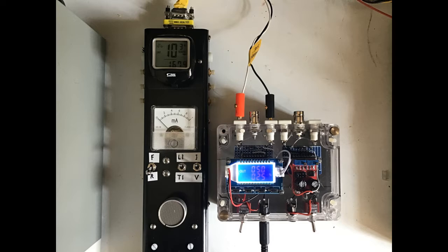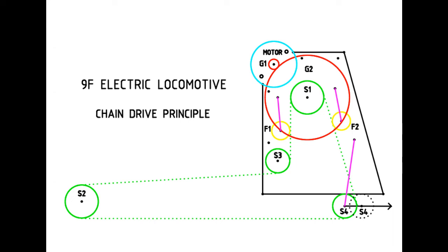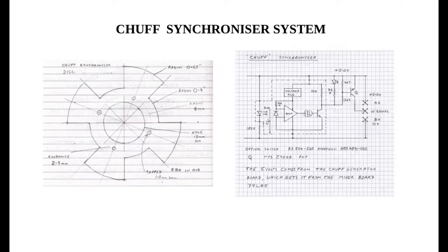I will now describe the chuff system. I was interested to see if I could produce a reasonably realistic sound of the steam exiting the cylinders synchronous to the piston position. The first decision was to use the same sprocket size for the centre axle and the sprocket in the gearbox. Since the gearbox shaft therefore moved in synchronism, I was able to fit an aligned 4-arm sector to it and use a slot-type optosensor to set the start and duration for the sound.